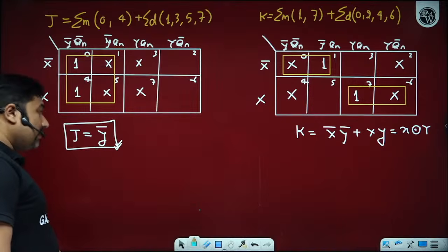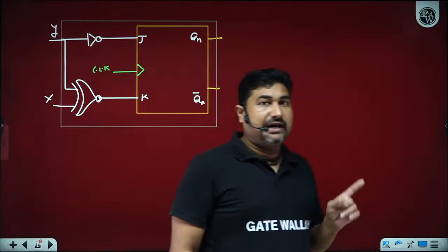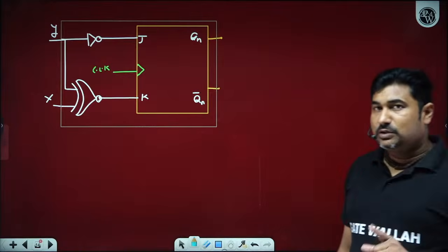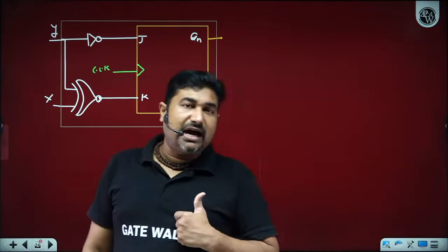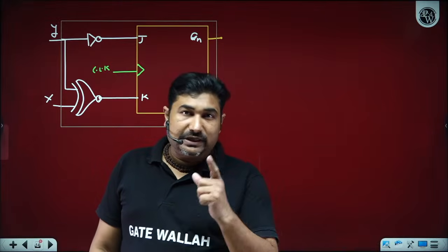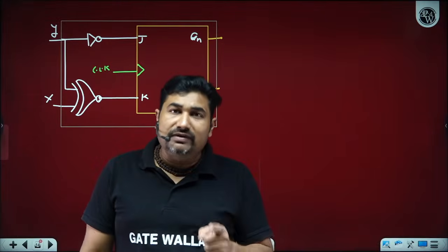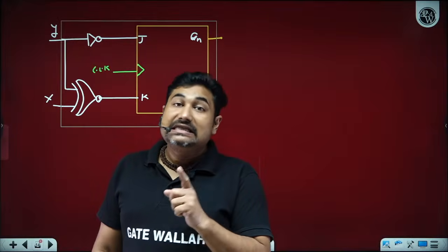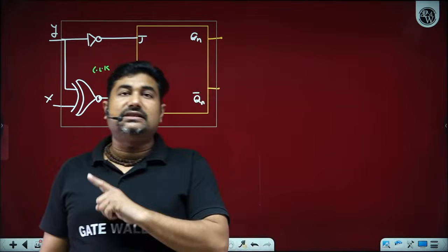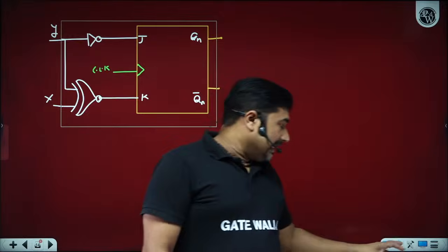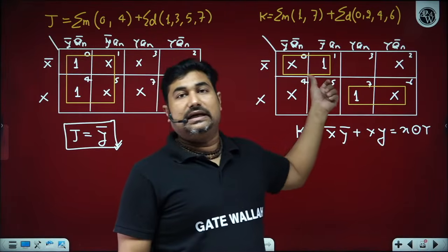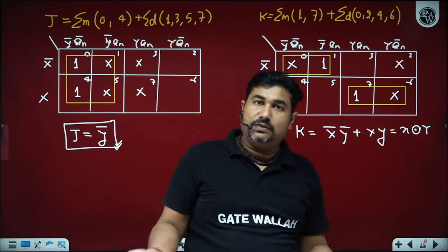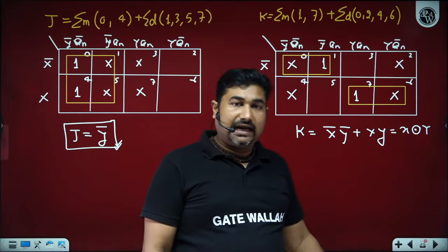In the K map solving, I told you, don't care may be logic 0 or 1, depending upon our requirement, and our prime requirement in K map is to get the minimized expression. So we always select the logic of don't care such that it helps in minimizing the logical expression. And in the same K map, we can select some of the don't cares as logic 1 and some as logic 0. All these things I have already discussed.